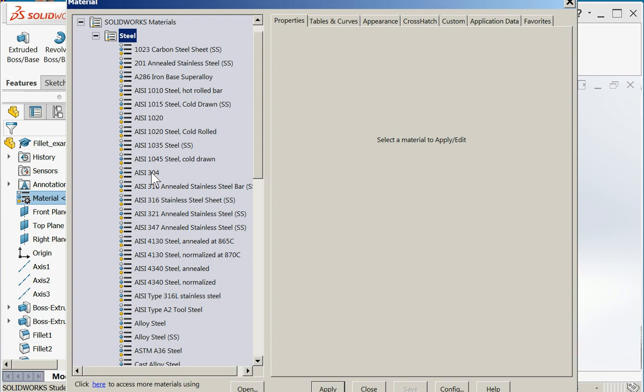There's a huge difference between something like 304, which is a very common stainless steel, versus something like 4340, which is used for aircraft frames, or 4130, which is used for gun barrels. And you certainly wouldn't want to interchange 4130 for something like 1010. If you make a gun barrel out of 1010 instead of 4130, it's going to blow up in your hand.